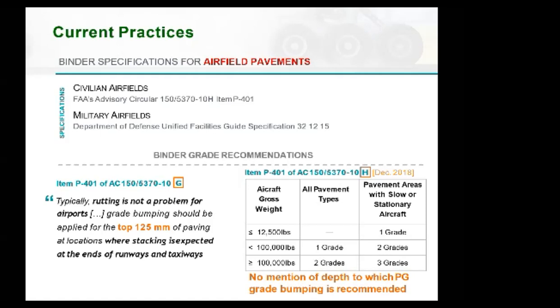Asphalt pavements sometimes reach a thickness of 50 centimeters. You could have very thick asphalt pavements. So what do I bump? Till where? You might have 5, 6 lifts: 2 lifts for surface, 2 lifts for intermediate, 2 lifts for binder layer. So which ones do I bump? Which ones do I not? There wasn't really a clear guidance on that.